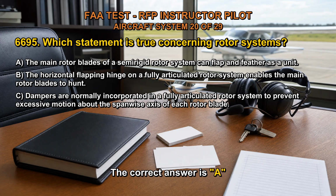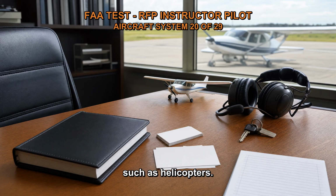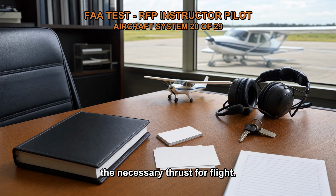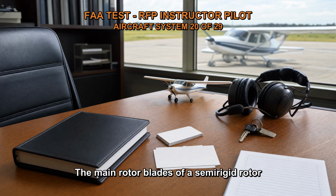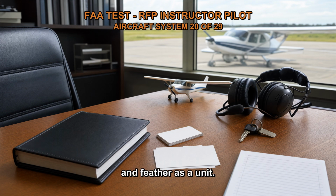The correct answer is A. Rotor systems are critical components of rotary wing aircraft, such as helicopters. They are responsible for generating lift and providing the necessary thrust for flight. Different rotor systems are designed with specific characteristics and mechanisms to achieve optimal performance. The main rotor blades of a semi-rigid rotor system can flap and feather as a unit. In a semi-rigid rotor system, the rotor blades are attached to the rotor hub using a combination of rigid and flexible components. This design allows the rotor blades to flap and feather as a unit.